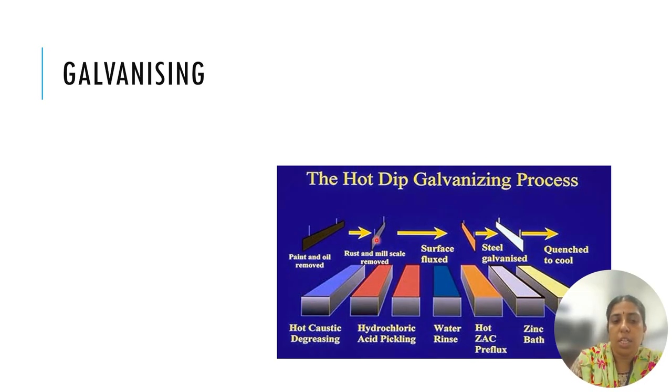It undergoes caustic degreasing, washing, the acid pickling process, and then it is dried and water rinsed so that the material is neutral, not acidic in nature. The material is then ready for coating of zinc, say for example any steel rolls or steel structures.